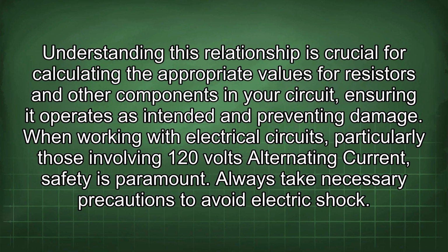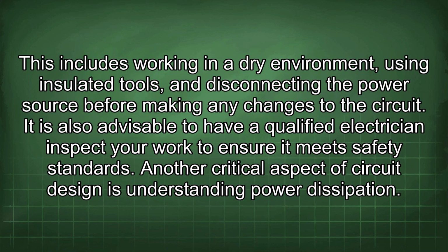When working with electrical circuits, particularly those involving 120 volts alternating current, safety is paramount. Always take necessary precautions to avoid electric shock. This includes working in a dry environment, using insulated tools, and disconnecting the power source before making any changes to a circuit. It is also advisable to have a qualified electrician inspect your work to ensure it meets safety standards.